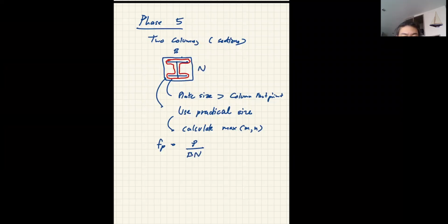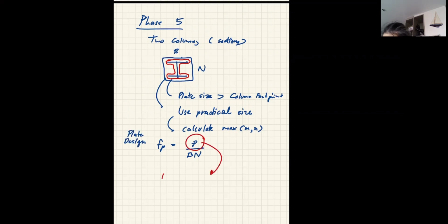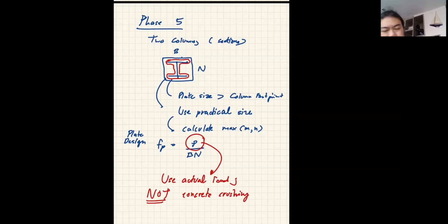One more thing, a common mistake is in the plate design: use the actual load, not the concrete crushing capacity of your abutment.